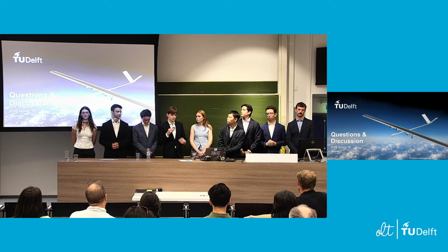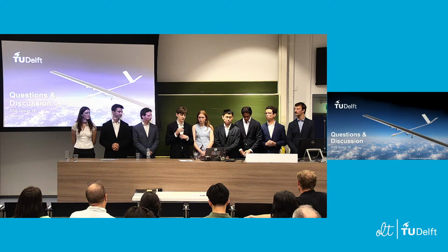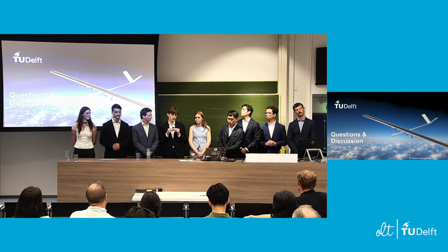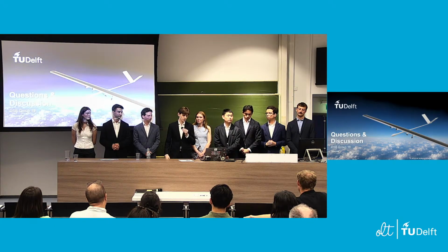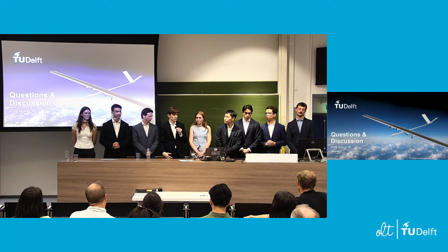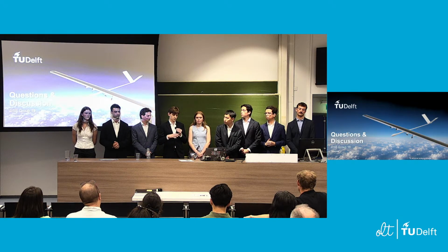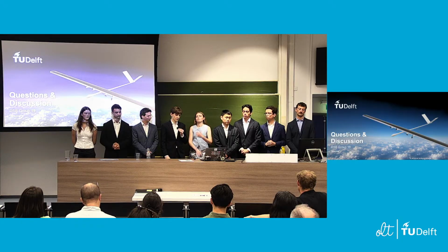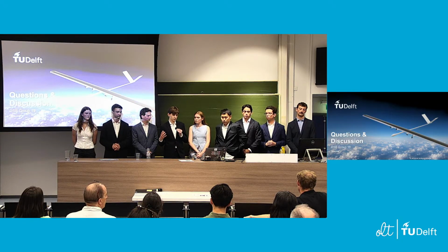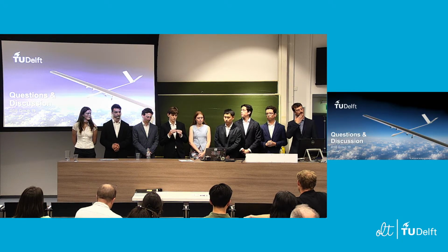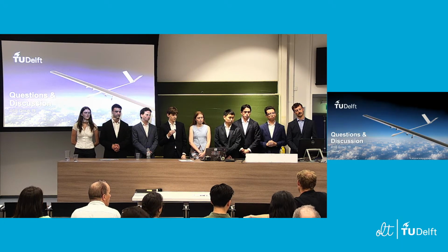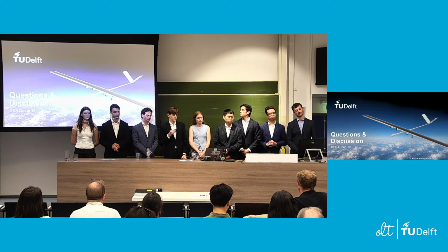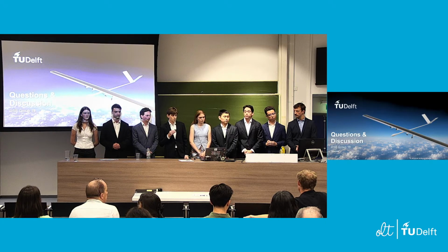And maybe just as a curiosity, I'll mention that we found a document where it was mentioned, based on a conversation with one employee of Airbus, that they estimated, if I'm correct, that after 6 months of using their Zephyr, the entire skin would have to be replaced because of degradation. So I think that would be one of the main factors. It is operational and maintenance related and not really endurance, because it can fly longer based on power and energy maybe, but there are probably other reasons limiting it.